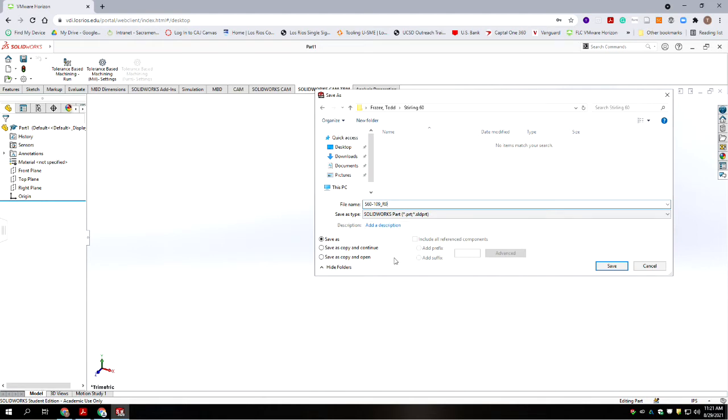Now if we had to go and update this part, the drawing might have a revision 1, 2, 3, or letters, depending on where it is in the design cycle. Many companies use numbers for prototype, and when they have solidified their design after building prototypes, they'll switch to letters, which designate its production revision. So you might have a revision 5, and then the next revision is revision A, and there's been no change between the two other than the revision.